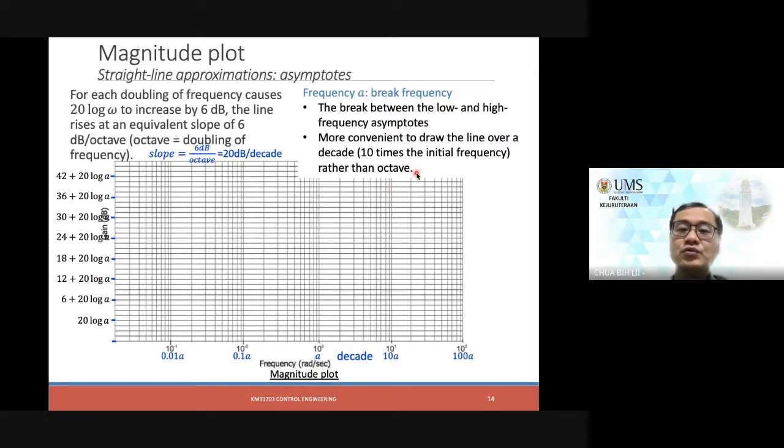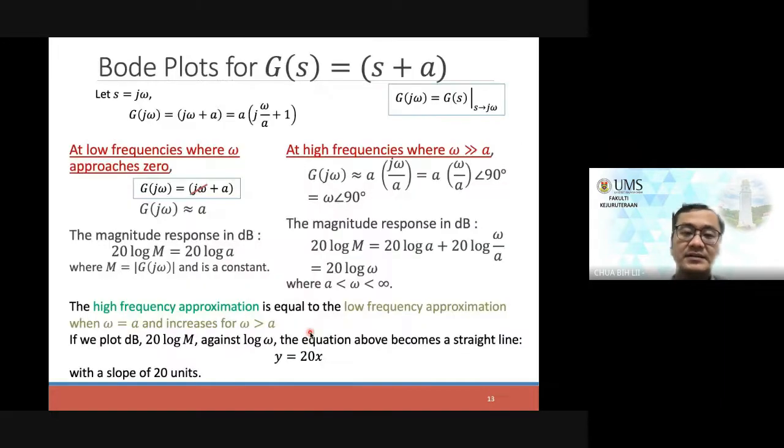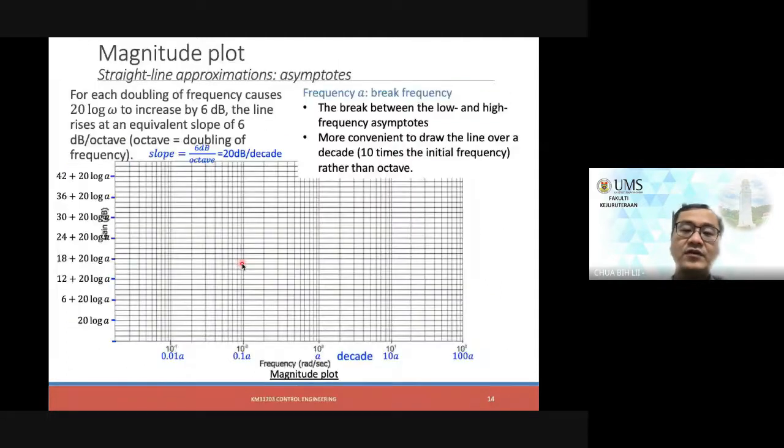So what we would do from this is define the low frequency region, which is before A. Because in our previous conditions, we said that this is the low frequency, when it's approaching 0, then we get A. The frequency is A with the magnitude 20 log A. Therefore, here we just plot for A and lower frequency than that, it will have a magnitude almost similar to 20 log A. That would be the magnitude. So this would be the starting point.